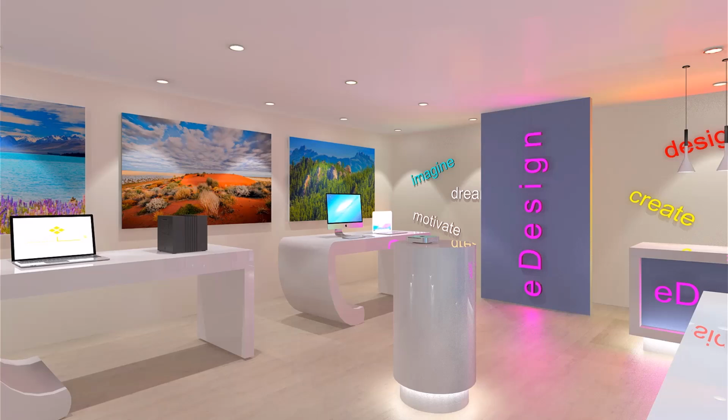Start a test render and work in 3 phases. The first phase is when we work with architectural elements. The second phase is when we work with furniture. The third phase is when we work with decorative elements. Within each phase, work in 3 steps. The first step is to assign appropriate styles to the surfaces. In the second step, start a test render and observe the materials. In the third step, fine-tune the materials.